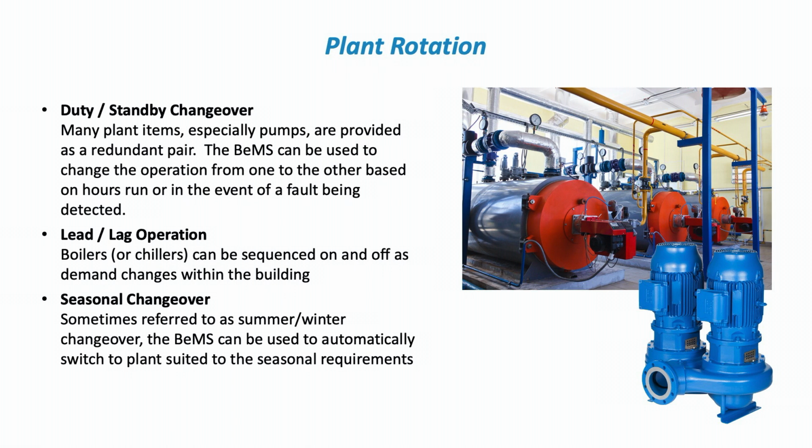But we can also use that to change which boiler is the lead boiler. If you just had number 1 as the lead boiler all the time, it would get much more wear and tear than boiler number 3. So we can actually change so that every week we have a different lead boiler so that we get even wear across all of our boilers.